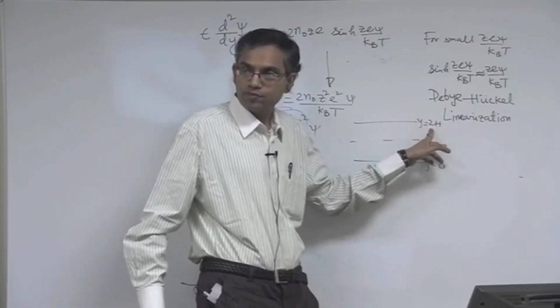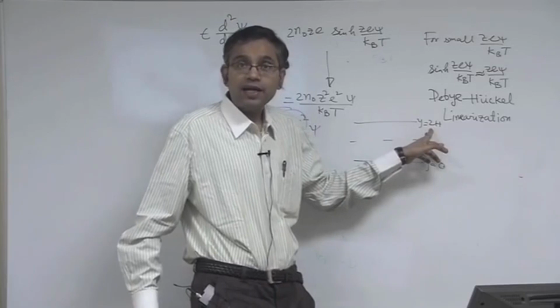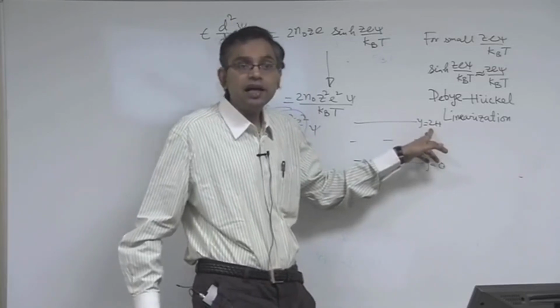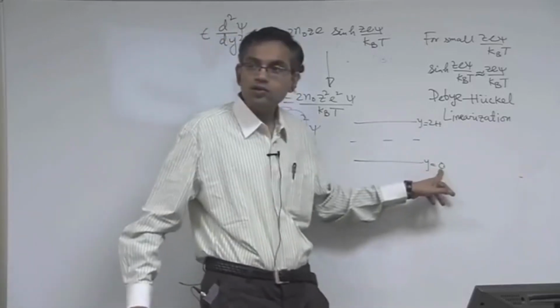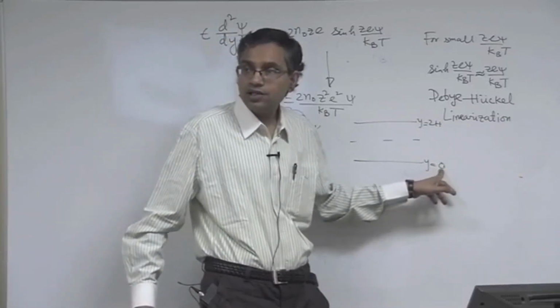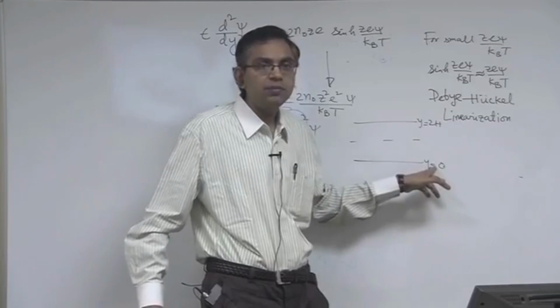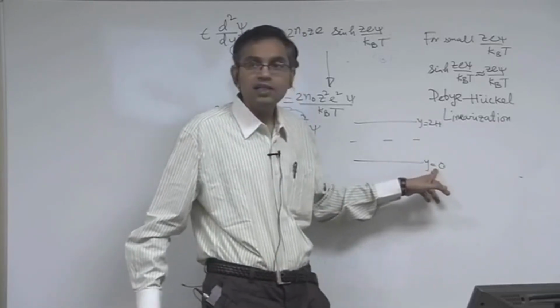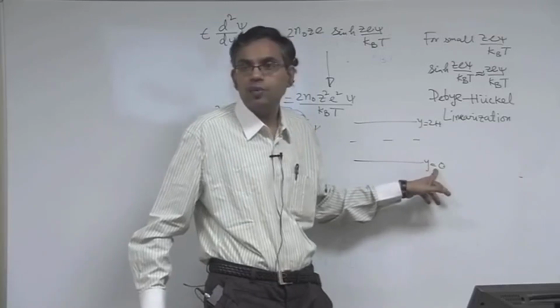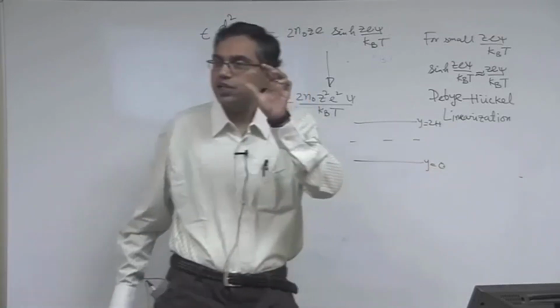Now technically there is an incorrectness in giving this boundary condition, because what is y equal to 0? Y equal to 0 is, let us say, the solid boundary. If this is the solid boundary, then the zeta potential is not the potential at the solid boundary, it is the potential at the shear plane.